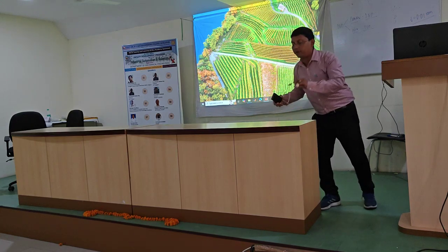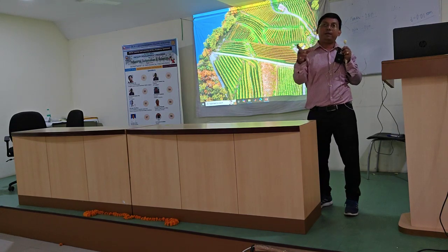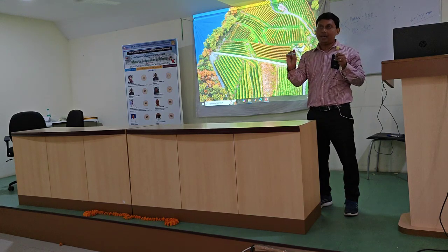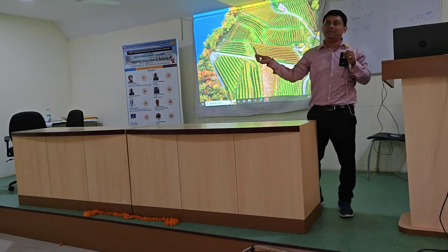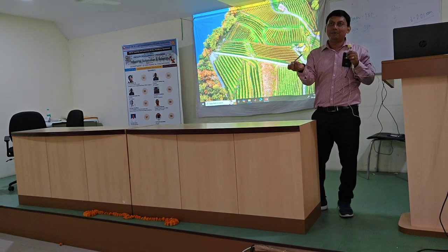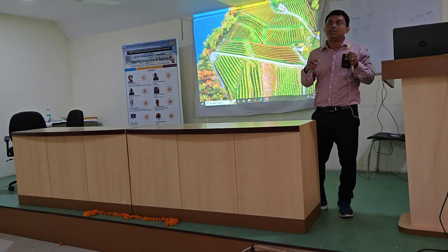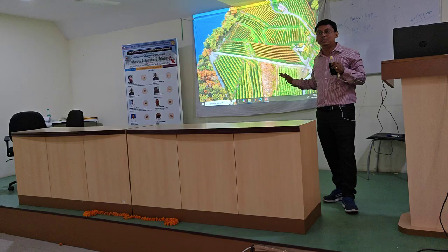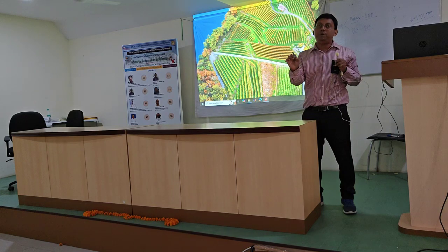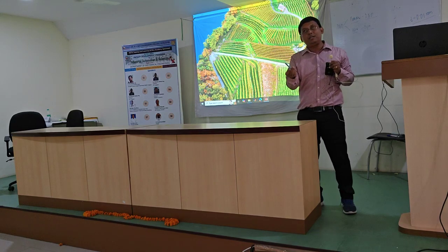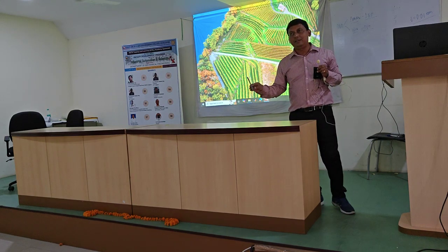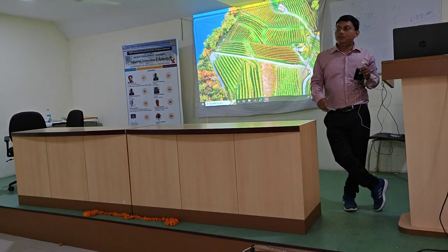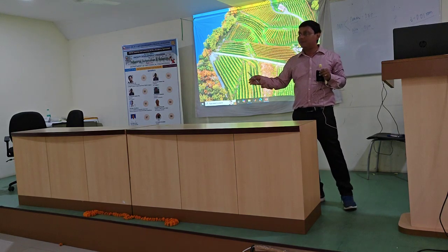But in a traditional manufacturing process, if you manufacture this particular pen using a die, and the die cost is say 60,000, then if you manufacture one pen, the pen cost will be 60,001 rupees. But if you manufacture 6 lakh pens with that die, the pen cost may be 5 rupees, maybe less. That theory is valid for traditional manufacturing because of the use of the die. But additive manufacturing is a die-less, tool-less process. So if you manufacture this pen by additive manufacturing, the cost is 20 rupees. If you manufacture one, it is 20 rupees. If you manufacture 500, each is 20 rupees. If you manufacture 6 lakh pens, each is 20 rupees, because there is no die cost or tool cost. All is variable cost. No fixed cost is imposed on it. All are recurring variable costs.